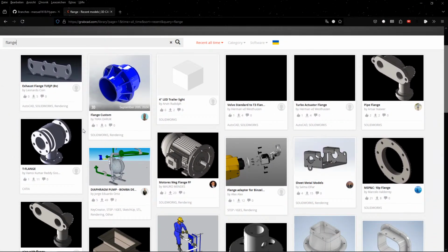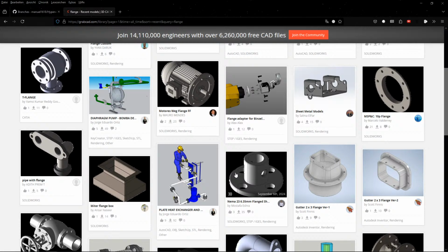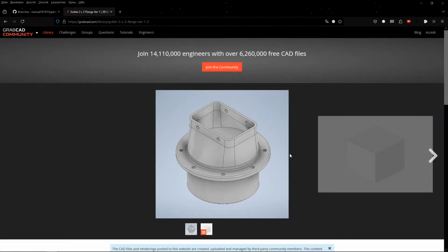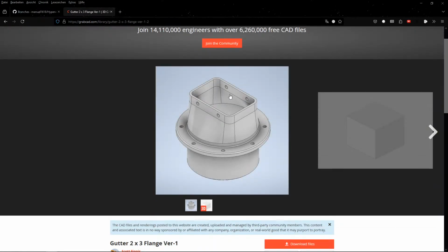You have some flange or some design like this, right? With many connections. For example, here you have maybe 8 connections or so. You would have to do this summation multiple times manually, and this would be quite tedious to do. So you do this if you have modeled the screws or the connections as rigid connections, right?